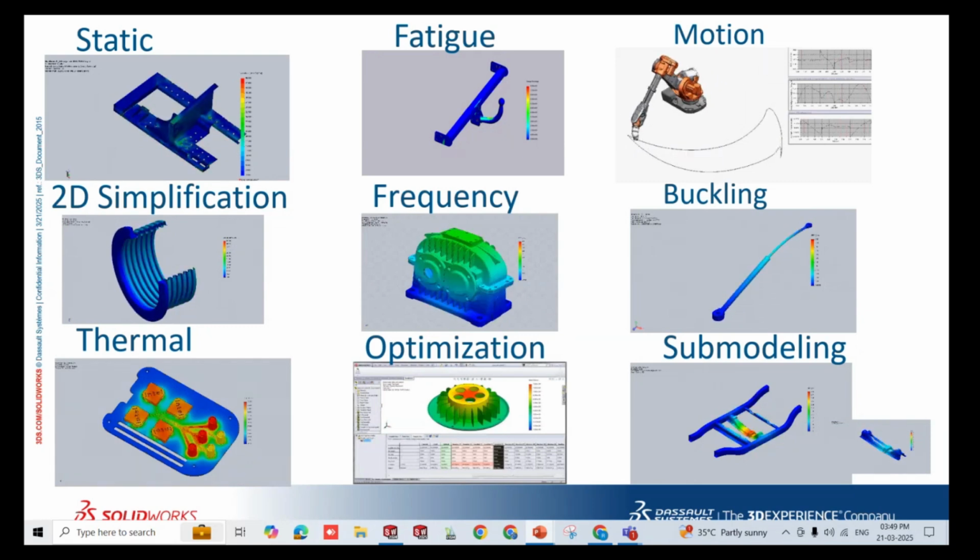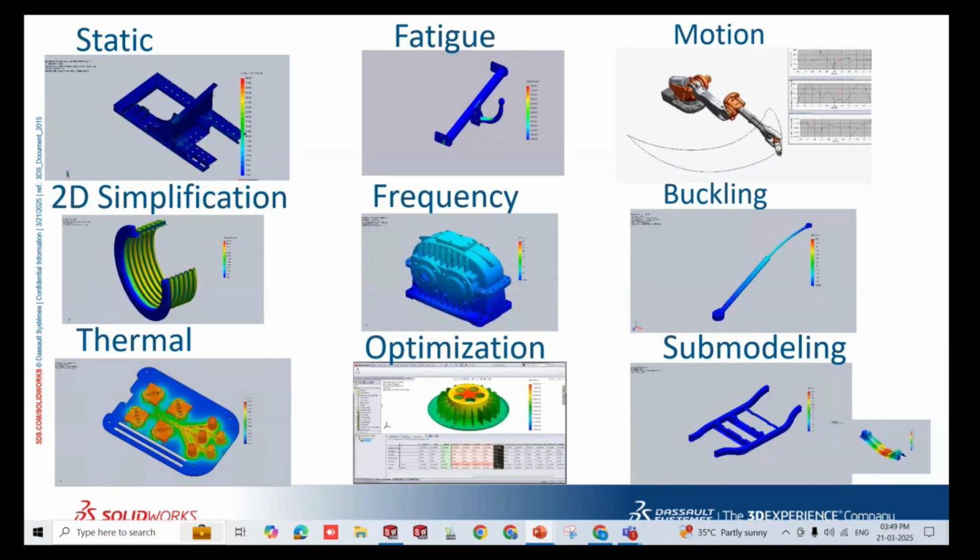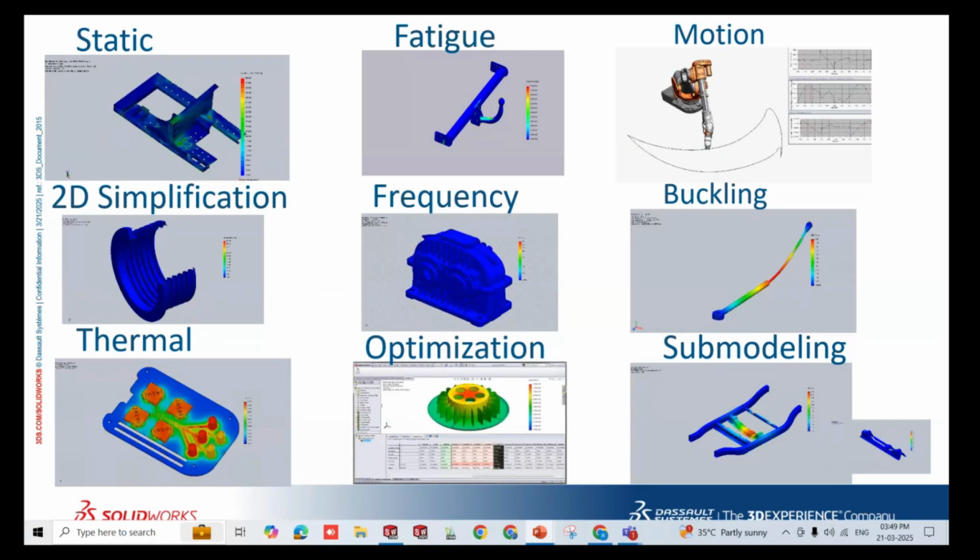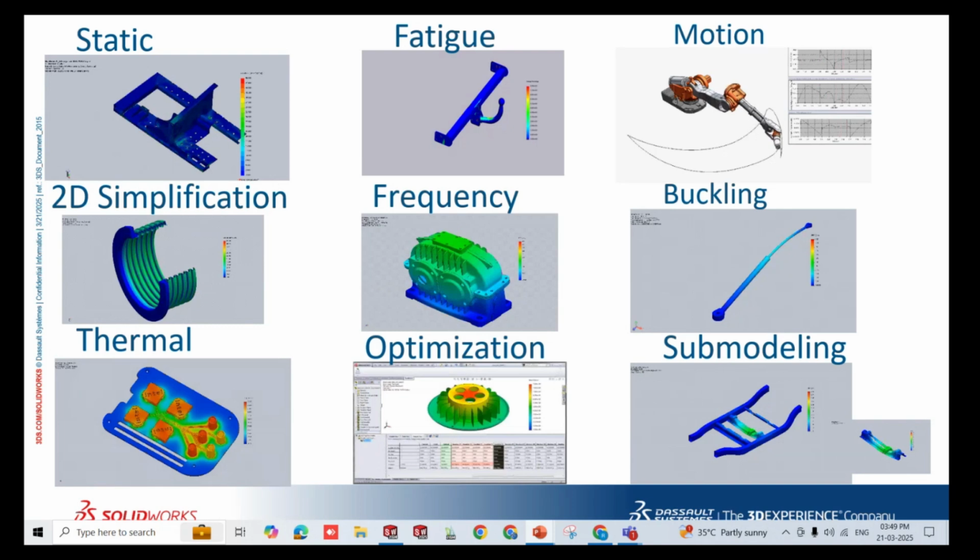Buckling is a failure, therefore it is quite critical. When a slender bar is subjected to compressive force, at some point it is going to show us some excessive sideways deformation. This phenomenon is known as buckling. Buckling is relevant if you have slender bars subjected to compressive loading. Can anyone tell me why we haven't performed buckling analysis for this crane?